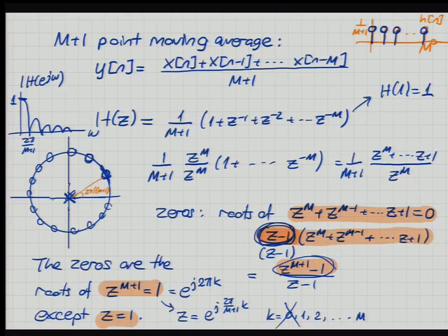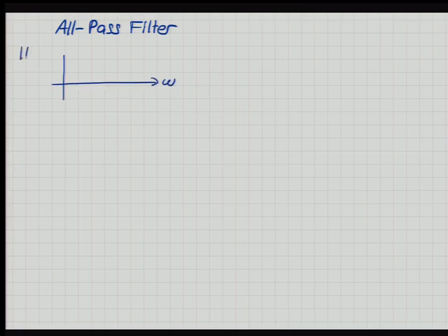All right, so one last small discussion before I let you go. All pass filters, what are they? You've seen an example. I don't know if it was a homework problem. I don't know if I called it an all pass filter then. I think I did. So this is a class of filters that does nothing to the signal if you look at the magnitude. So when you look at omega, I'm now on the left part of this board. I'm going to talk about the continuous time case.